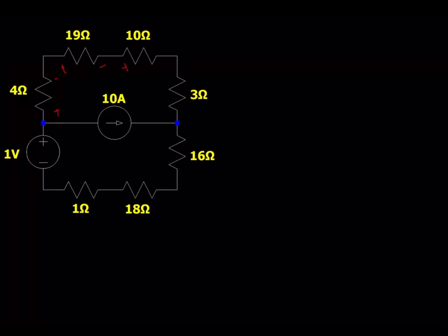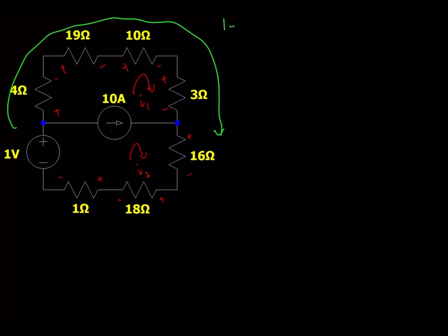So here I'm simply doing the mesh current method. I'm assigning these meshes a current variable, and then I'm creating two systems of equations, as well as that supermesh equation from the center current source. Again, you can use whatever method you like. The objective here is to find out what the voltage is at those two terminals.